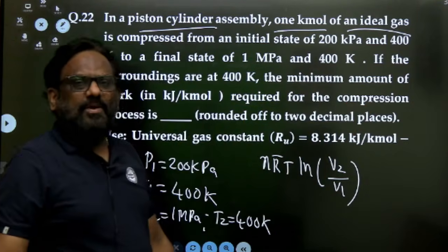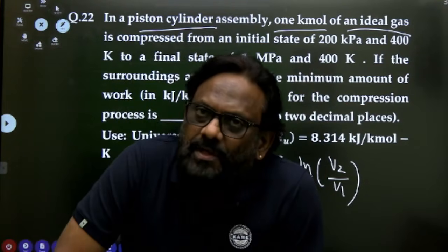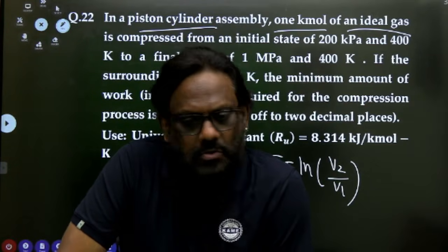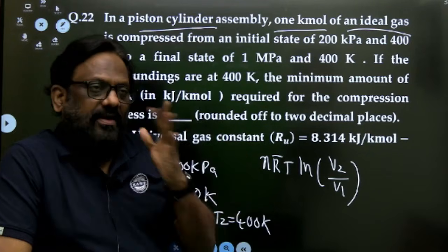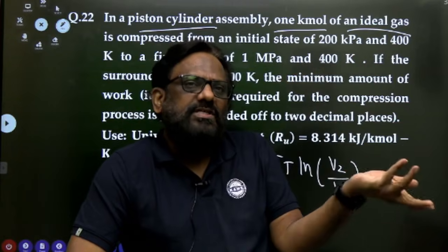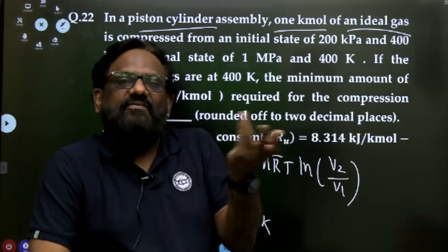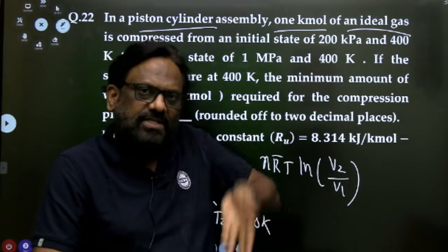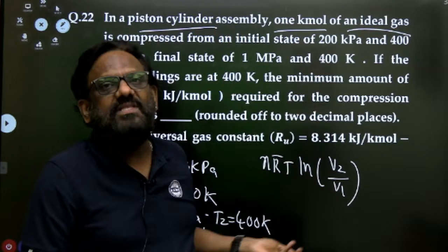And you know, for isothermal process, as it is a rectangular hyperbola, closed system work for an ideal gas is also equal to open system work. So कोई problem नहीं सर. Whenever देखो isothermal process के लिए, as it is a rectangular hyperbola, closed system work and open system works are same because a rectangular hyperbola is symmetric about x and y axis. When you project it on volume axis or pressure axis, it will give me the same answer.